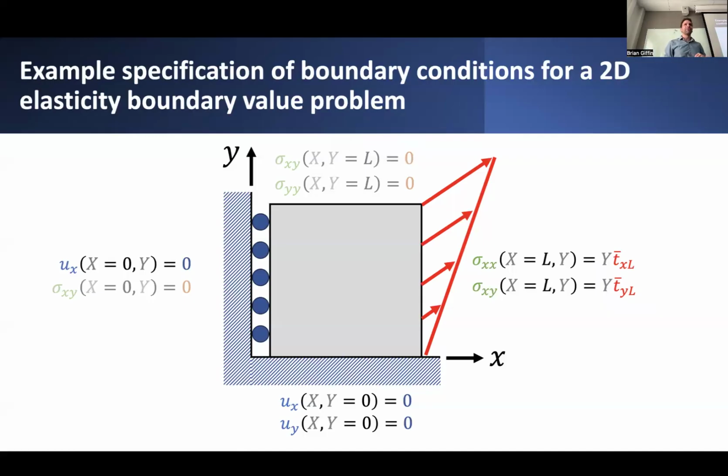And then finally, if we're applying a load, maybe that has components of stress both in the x and y directions, maybe it varies spatially and does some other interesting things, then we can represent these prescribed values of traction. In this case, the x component of traction, or basically the component of xx stress, exposed on this x-facing cut of this block, and also the xy stress, the shear face on that exterior face.